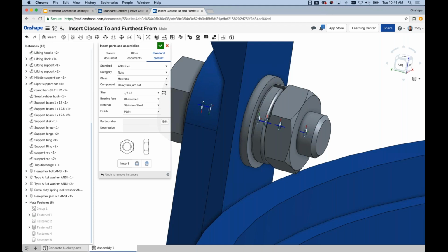How can I change the order of nuts and washers afterwards? Good question. Delete and reinsert essentially is the answer. If you wanted to move, well, I guess technically you could move the mates around if you wanted to, but I think it would almost be faster to delete and reinsert in that scenario. If you wanted to reorder this later, I would probably just delete and reinsert. Anything else would probably take longer than deleting and reinserting.